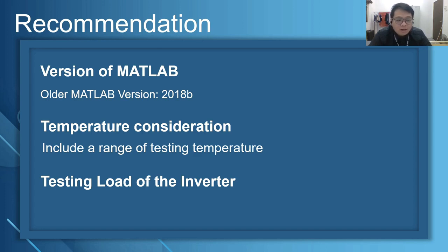The last recommendation is the testing load of the inverter. Matlab simulation has various functions, such as a built-in motor module for us students to study the working principle of the motor. So in future work, I recommend taking this opportunity of Matlab simulation by connecting the load of the inverter through motor modules. By using the motor module as the load, we can observe the resolution of the motor to obtain an even clearer image of the performance of the inverter, since the inverter of the electric vehicle is in charge of driving the motor of the EV.